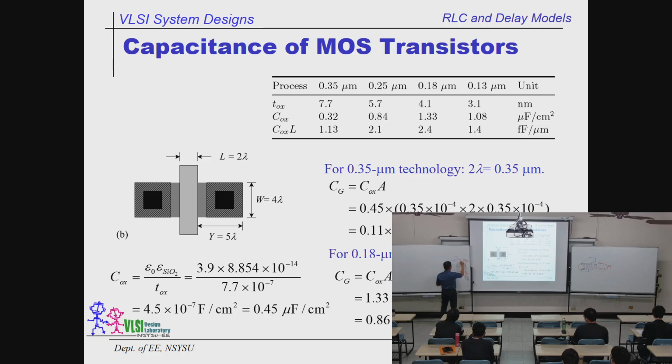This is about a 28 k ohm. And these, they are the same, 0.86 femtofarad. We have R, we have C. So we can estimate how fast the charging is and how fast the discharging is. Okay, you don't have to run the software. You can have something in your mind, how fast that could be. That is how we do it.